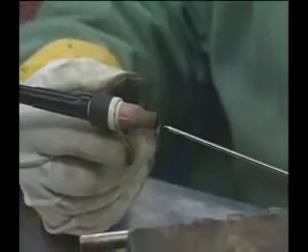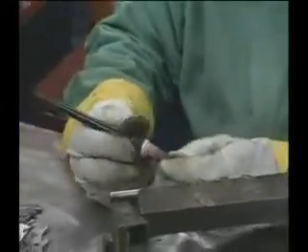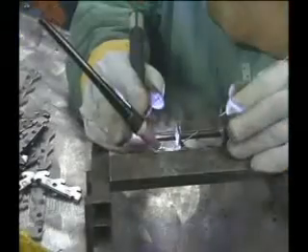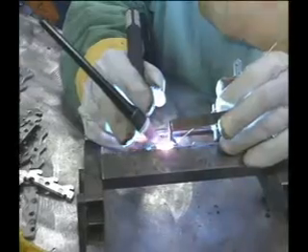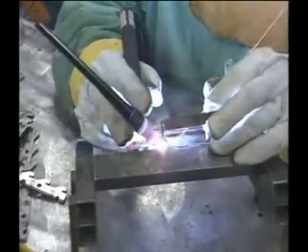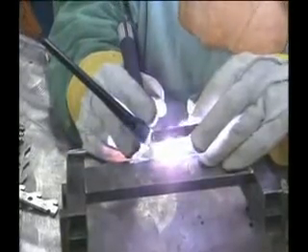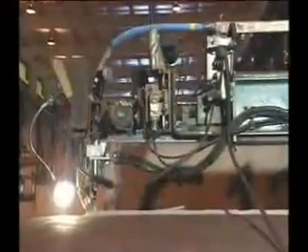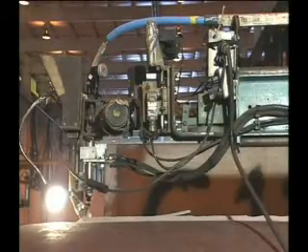The most common non-consumable electrode is a tungsten rod, which carries the electric current. If a welding operation using a non-consumable electrode also requires a filler metal, it is supplied by a separate wire, rod, or consumable insert. While welding, the electrode is moved either manually or mechanically along the joint, or the electrode is held stationary and the workpiece is moved.